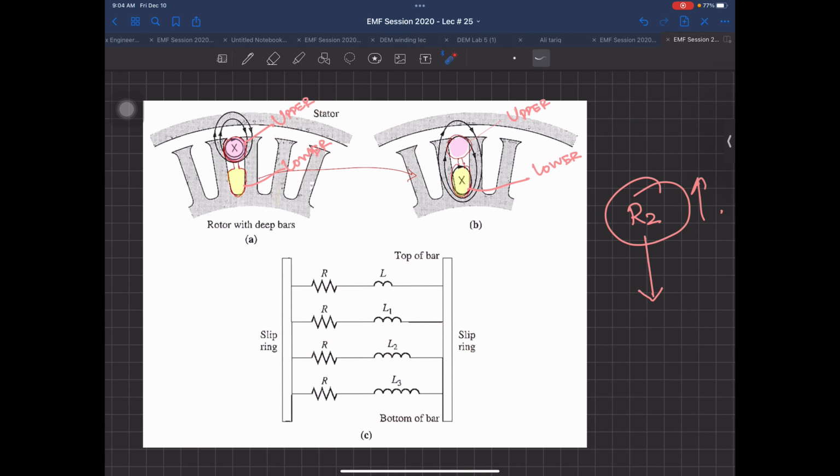It's just a physical representation, how to represent it, because you have put molten aluminium or copper here. So now this R and R and R, they all are the same. Now the point is still not achieved, that you have kept R also the same. Supposing this resistance was 10 ohms, for example, I'm just taking 10 ohms, it may be milliohms or microohms, it will be smaller. So all of these are supposedly 10 ohms, 10 ohms, 10 ohms. The overall resistance of one bar will be approximately 2.5 ohm.